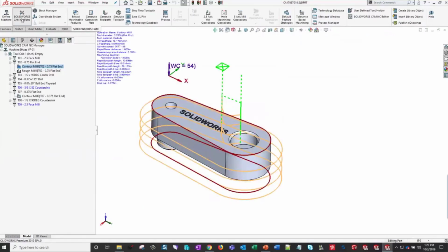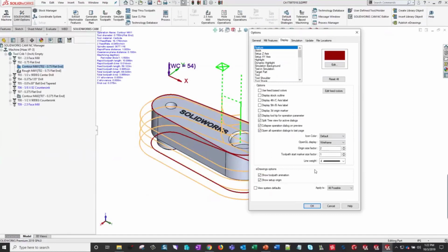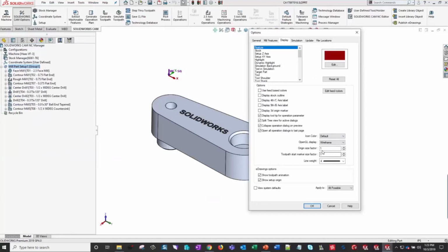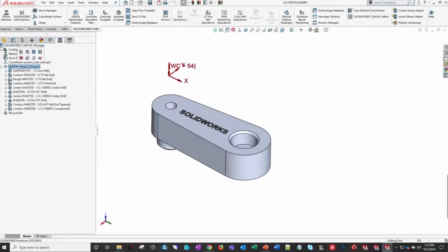So, getting into the options I was talking about earlier, this is where you can change your scale factor under display and your UCS icon here. I'm going to change this back to 1 just to show you. I'll click this back down, and I'll click here. Notice here's the size at 1. I'll go back here and change this to 2 again. Okay, and there's 2. I can see that a little better. I don't know about everyone else, but I think everybody agrees.